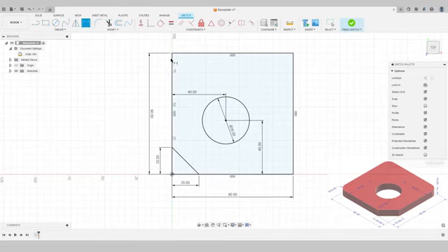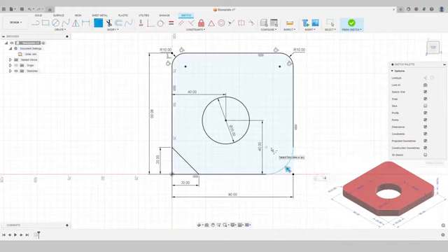And we've also got some fillets around this corner here, this corner, and this corner. Let's come up to the Modify tools and we'll select Fillet. Then we'll select this vertical line and this horizontal line, and you'll see a preview appear there. We've got an option to enter in the size of this fillet, which in this case is 10 millimeters. Press enter. We'll do the same for this corner here: left click the vertical, left click the horizontal, 10 on the keyboard. Same process for this corner here: horizontal, vertical, 10 on the keyboard, enter. And now I see that all of the entities here are black in color. Everything is fully constrained, and we're ready to finish the sketch there.